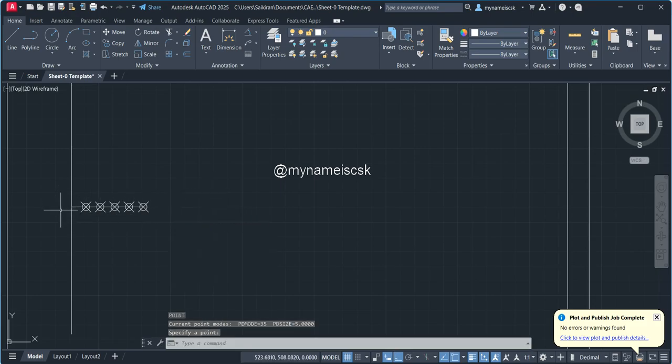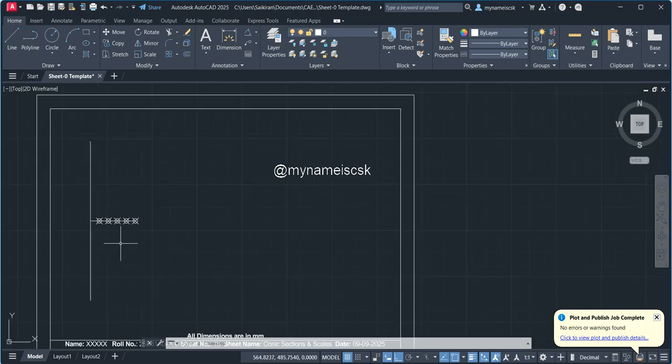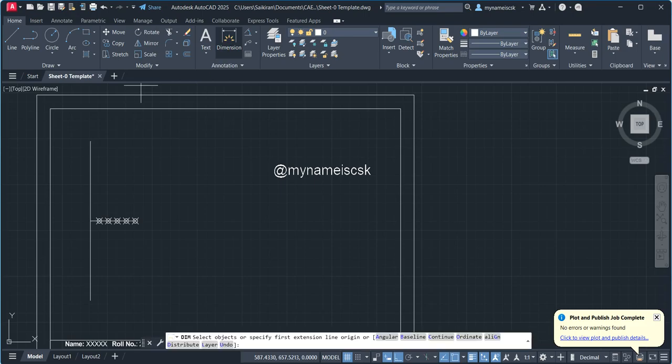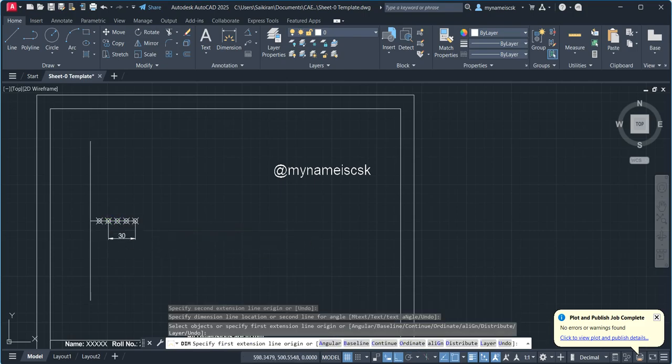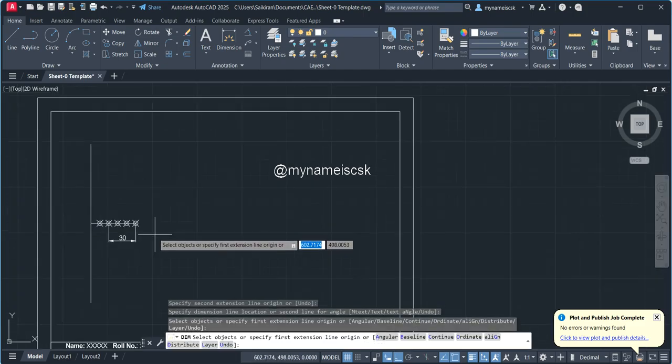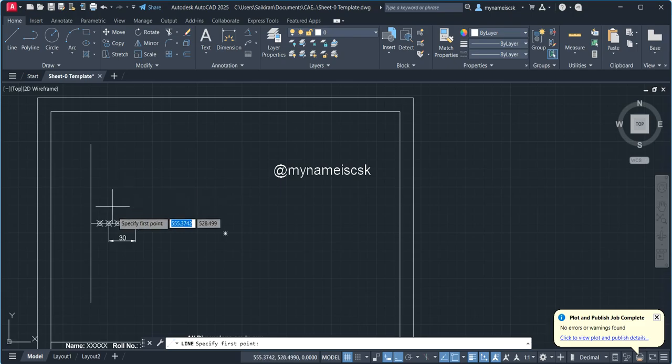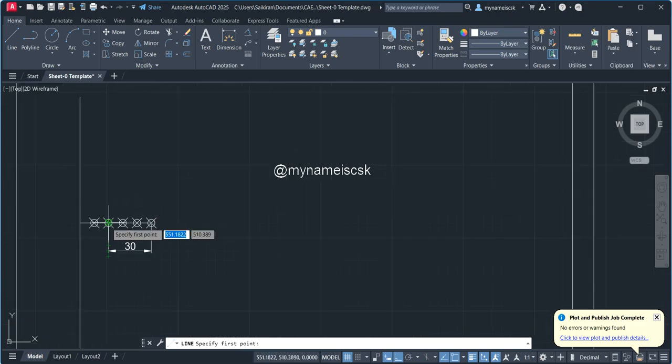Okay. So this is the C value, this is F value. Eccentricity is VF by VC equal to 3 by 2. So this distance is 3 points and this distance is 2 points. So 1, 2. So here I need to place my vertex. Vertex I need to place here at a distance of 30. Okay. So I need to place at a distance of 30. Okay. So E point also I have to locate at a distance of 30.